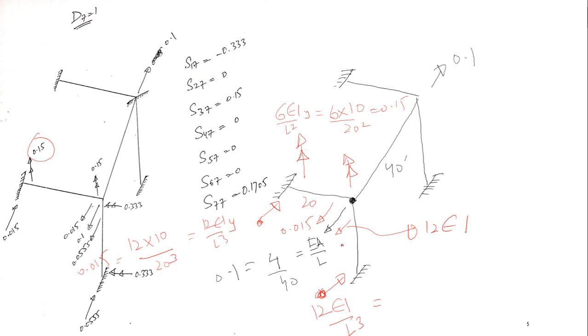No, you have to find the moments. This is y, this is z, so it is producing a moment in x direction. Y, z, x. Anti-resistive would be clockwise. Its magnitude would be equal to 6EIx/L².